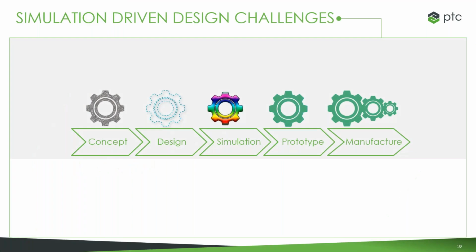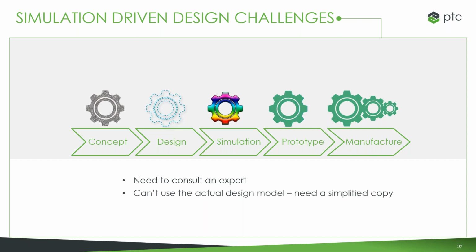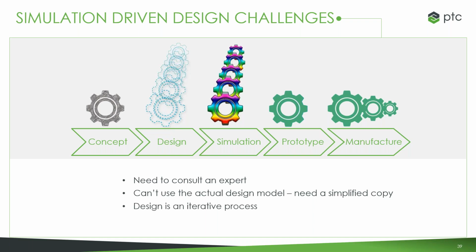All right. So I do want to discuss just a little bit of background on some of the challenges that this tool addresses with Creo Simulation Live. In the traditional way, if you want to do simulation in the design process, you'd generally have to consult an expert or at least be very knowledgeable in analysis itself. Also, we wouldn't be working with the actual model. We'd probably have to use a simplified version that's defeatured, with no small holes or rounds or any type of interferences. And as you might know, this process is very iterative. Every time you run the simulation, you need to go back into your design, make changes, and start the simulation over again. This whole process just takes a very long time.